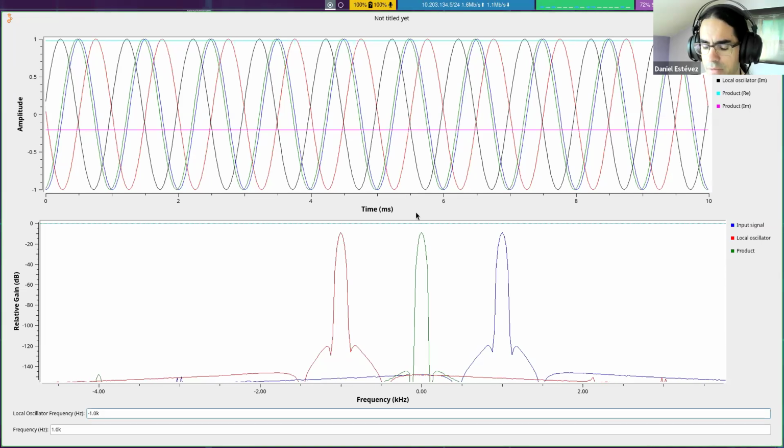Even physical receivers like the RTL-SDR stick you have, there are some electronics in there doing operations which are similar to this. The signal which arrives at the antenna on the RTL-SDR is definitely going to be a real signal because it's a physical quantity. It's going to be a voltage. So that's like a single real number, which changes over time.